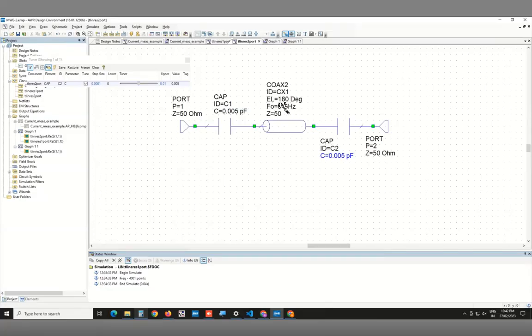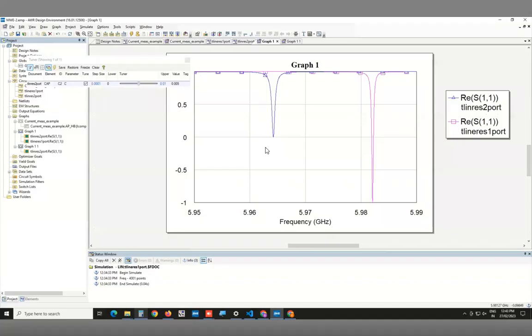So if you remember, we had discussed this, I think, in the context of LC circuits with coupling capacitors, but also in the context of the resonators as well, but maybe we didn't spend too much time. So this capacitance has a sort of a loading effect, that if you model your resonator as just a parallel LC circuit, this extra capacitance, which is the coupling capacitance and allows you to control the Q or the dissipation, also shifts the frequency because that capacitance adds to the total resonance. So now, because there are two of them, they will add together and shift the frequency more. That is why this frequency is further shifted from 6 gigahertz.